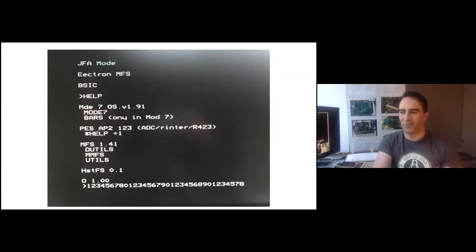Here is mode 7. Well, mostly working. This is what happens when you get the clock wrong. The FPGA I used has block RAM, but it doesn't let you initialize the block RAM. With the Spartan 6 that you're probably familiar with, you can initialize your block RAM. You can say, I need 16K of memory, and it should start out with the contents of the Electron's OS ROM. Can't do that with the Max 10, at least the compact feature version, which is the affordable one, which only requires one power supply and not three.